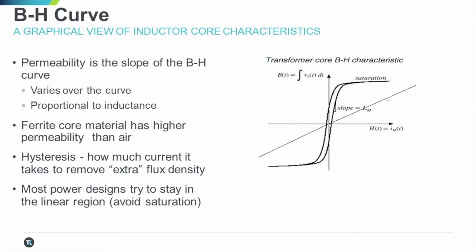Another consideration is the saturation flux density. This is the point at which additional magnetizing force no longer produces flux density. As you can see with the figure in the above equation, saturation is reached at the point where the slope flattens out. So again, no matter how much more magnetizing force you insert into the device, you will not produce any more flux.